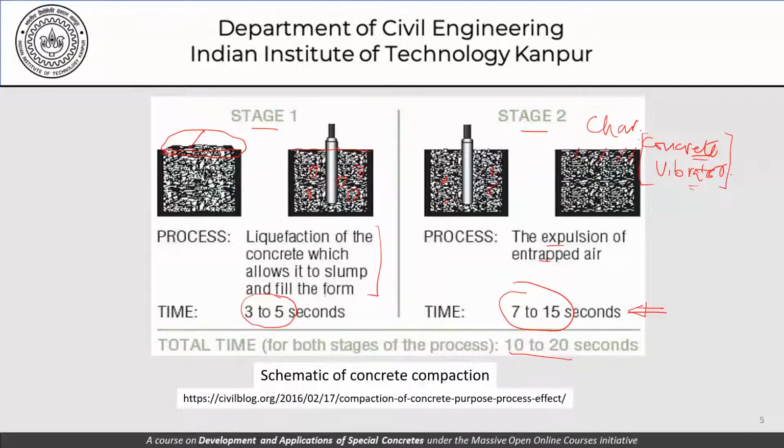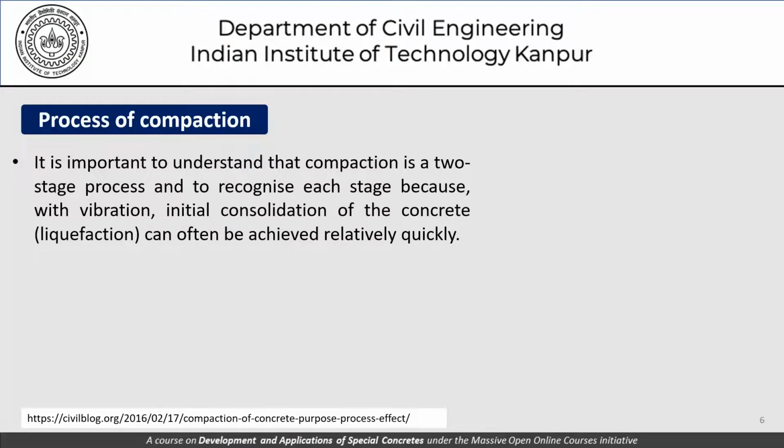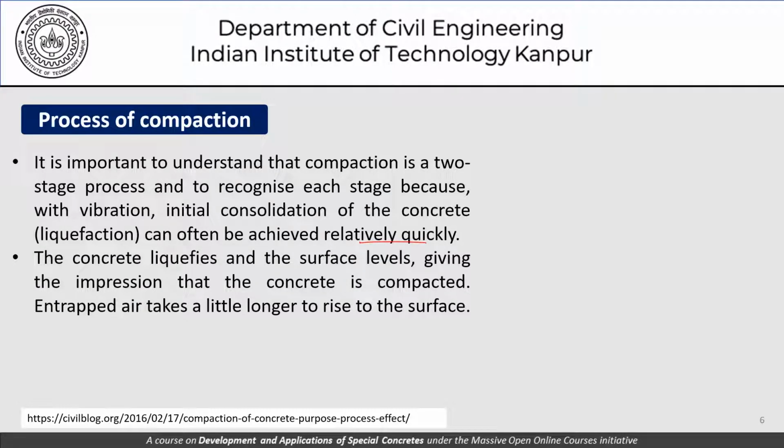The process of compaction, once again to reiterate, it's important to understand that compaction is a two-stage process and to recognize each stage, because with vibration, initial consolidation of concrete can be achieved relatively quickly depending upon the type of concrete that we are talking about, and concrete liquefies in the surface levels, giving the impression that the concrete is compacted, but entrapped air takes a much longer time to rise to the surface.